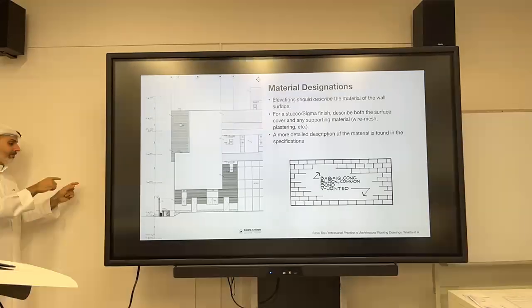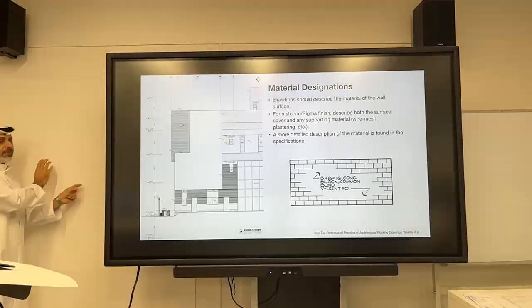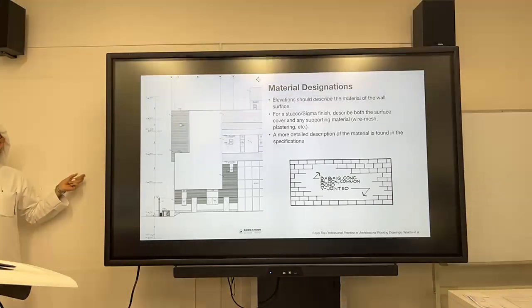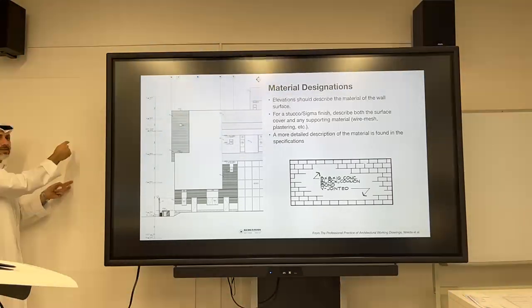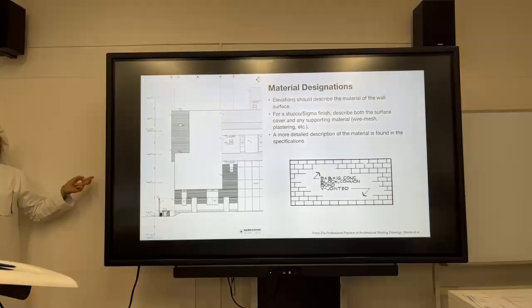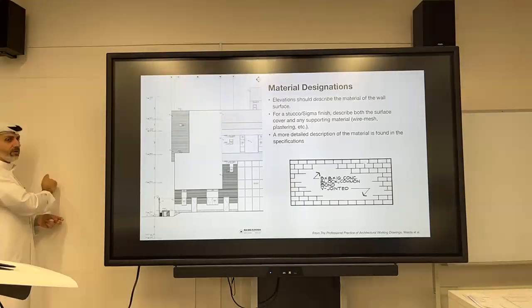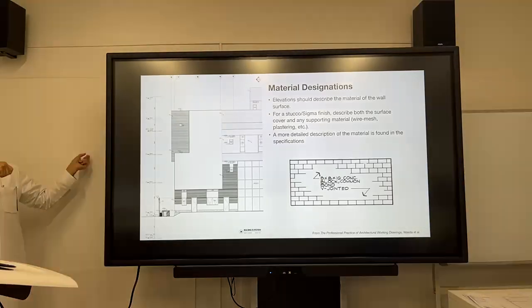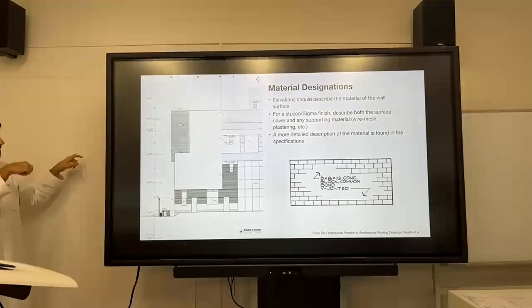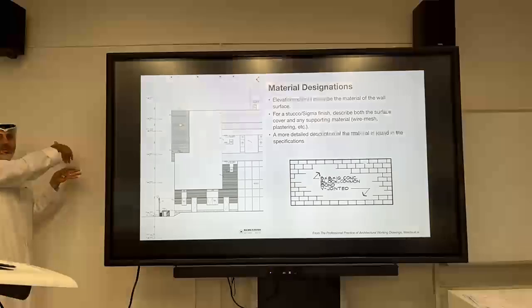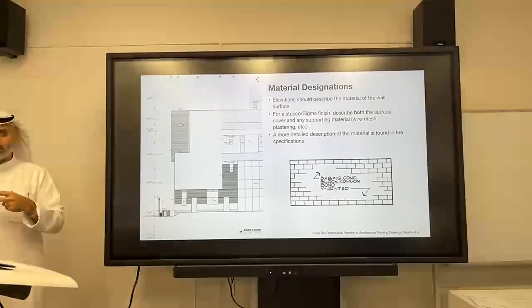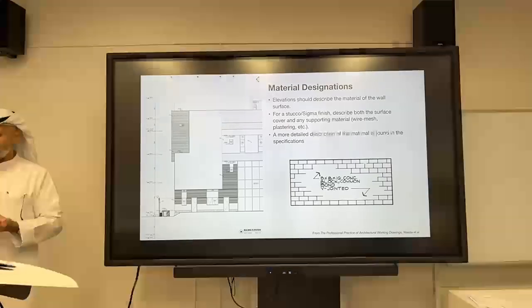Semi-mechanical is when you have the stone, and the material behind the stone has to be the stronger brick, so that you can put the supports of the mechanical system. Semi-mechanical, which is more common in Kuwait, especially smaller projects, has nails in the brick. Then they tie steel wire to the stone in a specific way. And once they do that, they fill cement behind it. So when you knock on the stone, it's going to feel solid. So it's semi-mechanical. Then it's half mechanical, half cement. That's why it's called semi-mechanical.